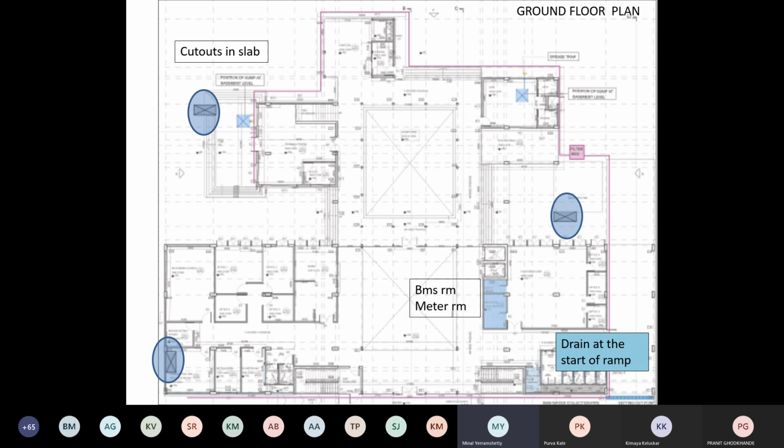I will be giving a big opening, 2-3 feet, maybe even more, 1 meter, I don't know, depending on the calculation of the ducts which your consultant will give you. Based on that, the duct will have to come out at the ground floor from the natural air outside. It is going to suck that air in and then throw it into the basement, and call itself a plenum room. Is that the job of a plenum room, right?